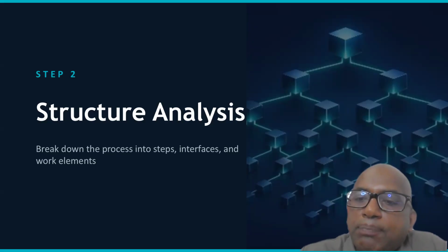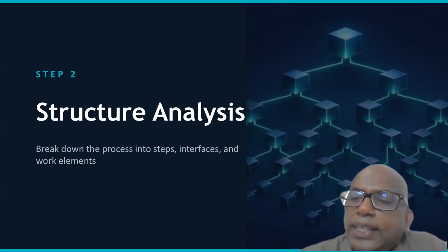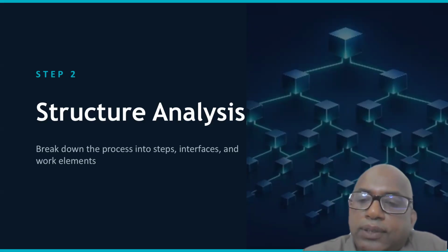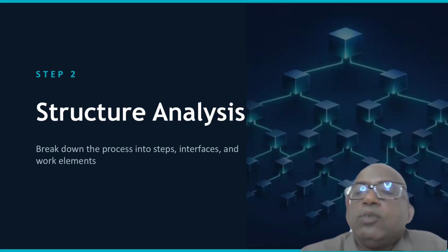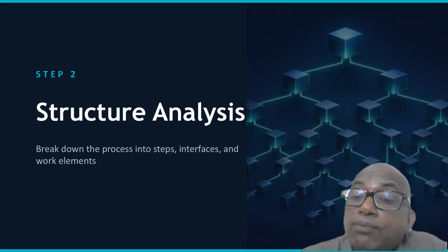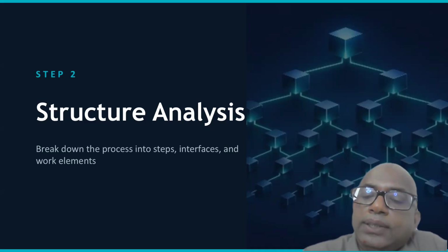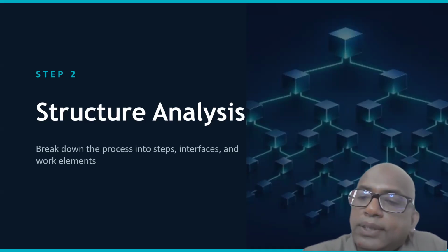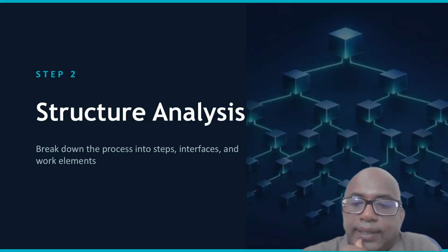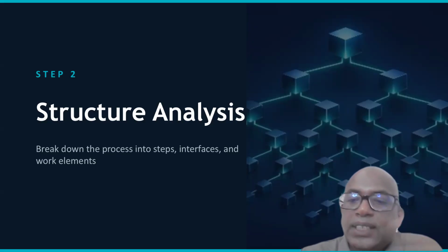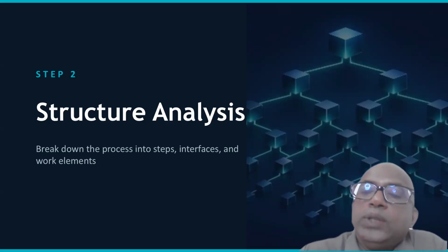Each and every step of the process you have to clearly define. Then you go to work elements, the individual activities of your process, and for each individual element you have to find the failure modes. This is a very specific approach, because no failure mode is missed after doing this new version of PFMEA.